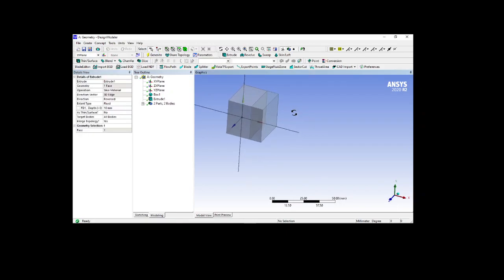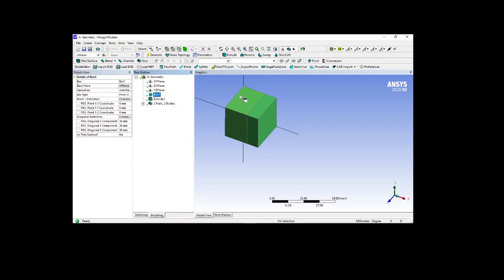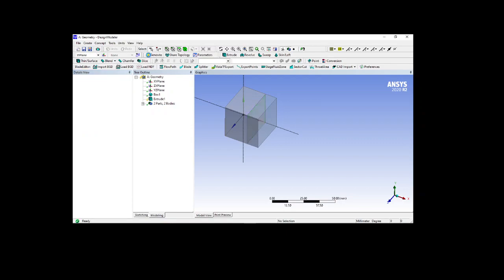As usual, it will create two different geometries. The first one is what we have performed, and another one is the box. Slice is also like a virtual operation, not exactly what we want. But the add material, frozen material and cut material are the actual operations we have to do. I will use frozen here, so I will generate it because we have some more operations to see.